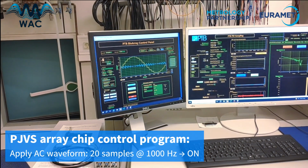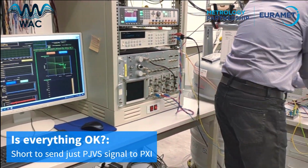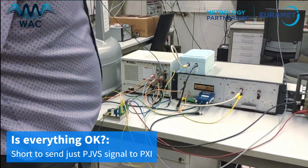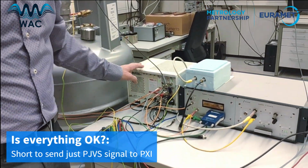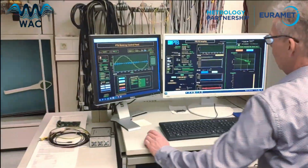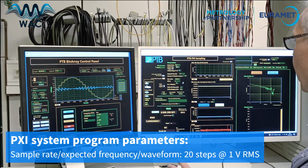Okay, now the microwave is on, the signal has been sent. What I have to do now is to put a short here first. So I'm just sending the stepwise Josephson waveform to the PXI to check if everything is fine with the system. I'm using our program for differential sampling and differential subsampling.